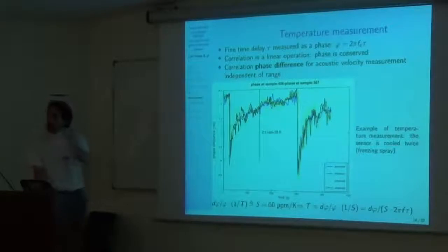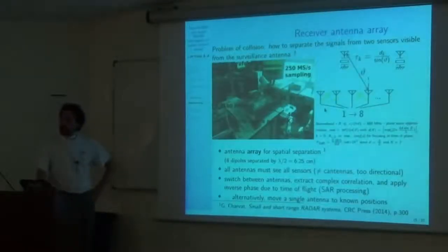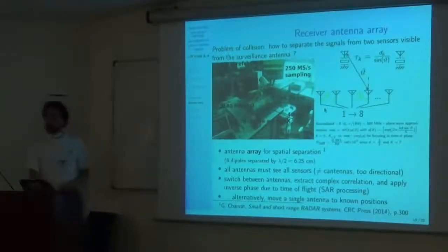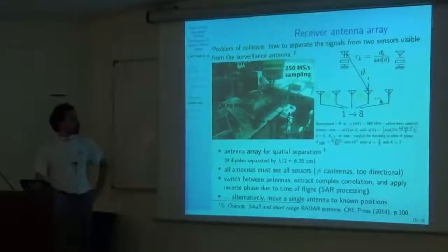Now, just to get you interested, and I don't have time to get into the details, I just want to show you that we can do passive radar not only for range and velocity measurement, but also direction of arrival, as we've shown earlier with the active system, except that I'm doing this with a passive system. I have a Wi-Fi emitter. This Wi-Fi emitter is illuminating a target, and the target signal is collected not with one antenna, but with multiple antennas.